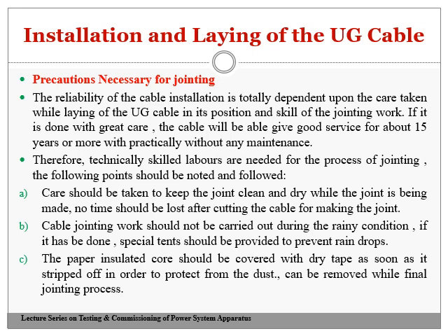The following points should be noted while jointing. Care should be taken to keep the joint clean and dry while the joint is being made. No time should be lost after cutting the cable for making the joint. Once you cut the cable, jointing should be started immediately. Otherwise, moisture will enter into the cut cables. It will cause unwanted disturbances because of the moisture entering.